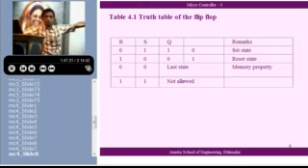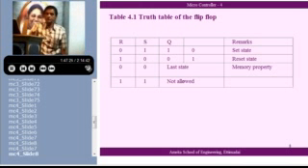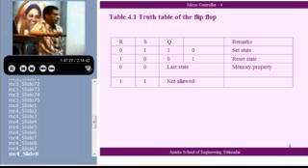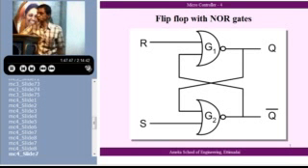In fact, the subsequent operations are all done such that that next state will be avoided, because that gives a problem that is avoided. So I would like to encash, see, my job is not to see in what all ways I can use. My job is to see in what all useful ways I can use the gates. The useful way I can use the two gates is to have the memory property. To have the memory property, the simplest way of doing it is use two gates. Use two NOR gates, connect them in this crisscross fashion.